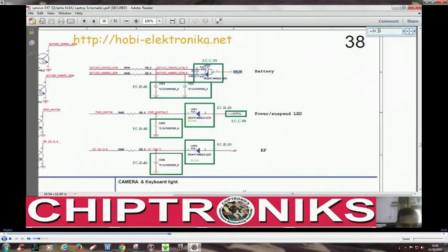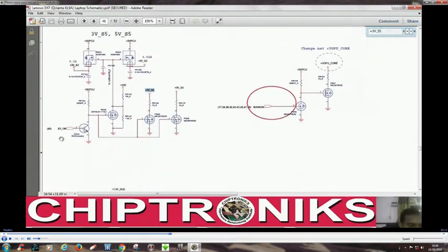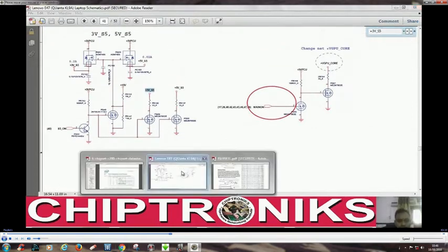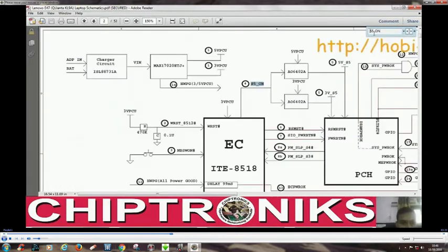We'll check. So let's go find where this is provided. Yeah, now you can see this +3V_S5 is generated from the +3V_PCU. Let us zoom it to understand this, right? Now this S5_ON is generated from the IO controller. We can see there is nothing hidden over here. We just go to the page number 40, or we can just search S5_ON.